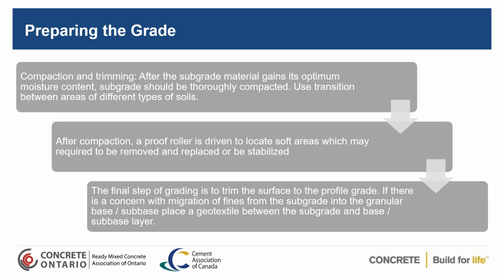The final step is your profile grade. And when you're doing this, you're going to look at if you have a situation where your subgrade has the possibility of fines migrating up into the new granulars that you place on it, you'll want to put a geotextile down, and that will prevent the migration of the fines, which would contaminate your granular base and subbase layer over time, and would change the performance of your pavement because you're now weakening the